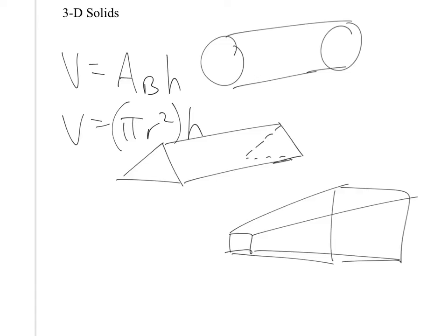If you want to make a pipe in 3D CAD, you want to make ductwork and piping system, you make 2 concentric circles. And then you only take that wall thickness and extrude that. You don't extrude the middle. See what I'm saying by that? So if you wanted to make a pipe with an opening, okay, you shade in this region, or you select this region in CAD, and you press extrude, and it will extrude it by a certain dimension. It will leave the middle of it open, like that.